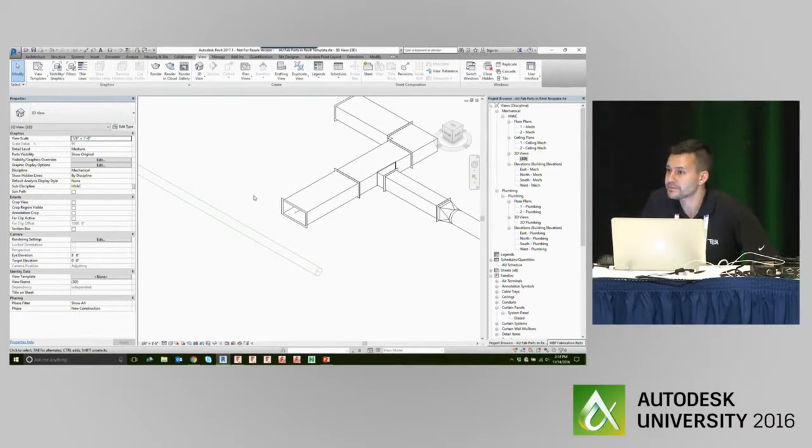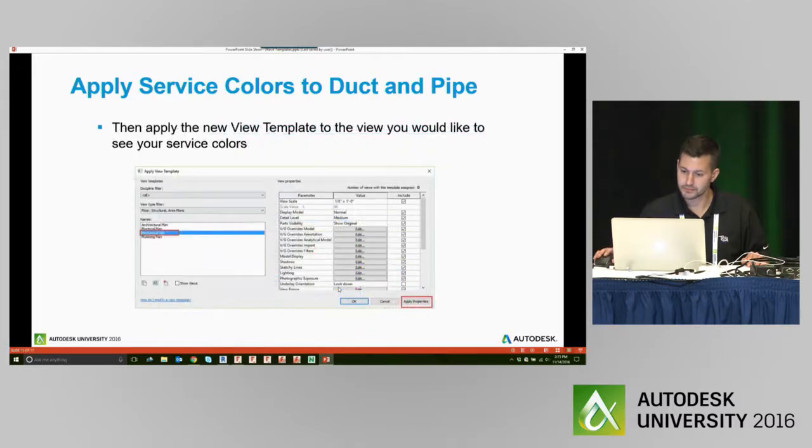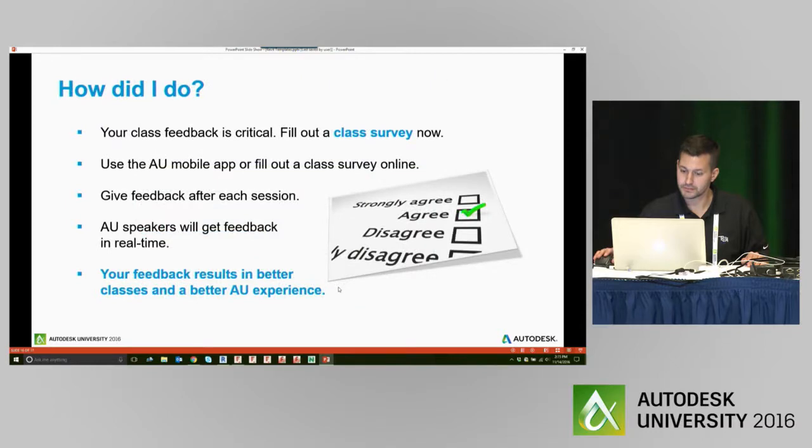Will those colors transfer over to Navisworks? You know what? I haven't tried it from Revit yet. Yeah, you have to apply material to get it if it's a Revit family. If it's a Revit family, yeah, but fabrication part, that's the only way to get it over as a material. Yeah, exactly. Similar in Navisworks where you set up search sets and override the color in Navisworks, kind of a pain in the butt.